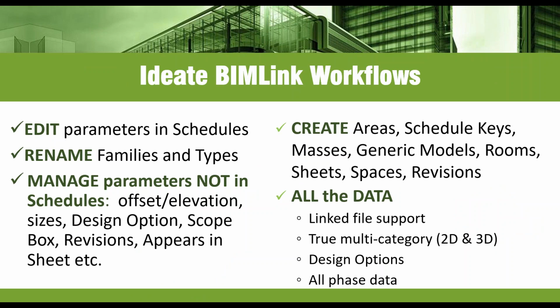What I'm showing you right here is just a small sampling of what BIMLink can do. You can edit data, or you can edit parameters within your schedules. You can create new areas and schedule keys and rooms and sheets and spaces if you want to. Also rename your families if you want to. And then we also give you access to data that you normally will never see in a Revit model.